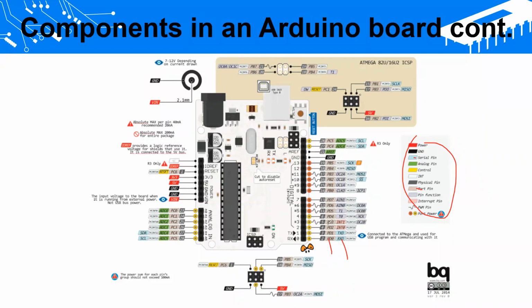Then if you consider pin number 3, we have this color that is basically for interrupts. We're going to discuss that part today, right? Then in here you can see it marked as this kind of a curved thing. So obviously this is a digital pin, right? And if we have this color, that basically means it can act as a PWM pin. If we need that functionality, we can get it from this pin, right?